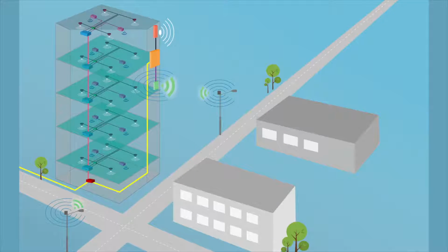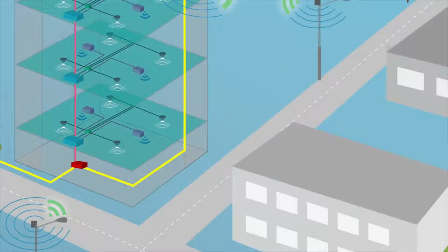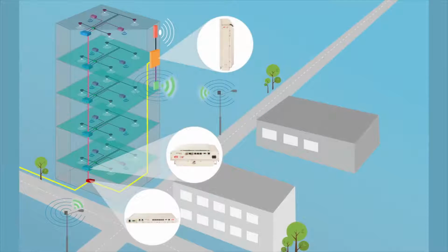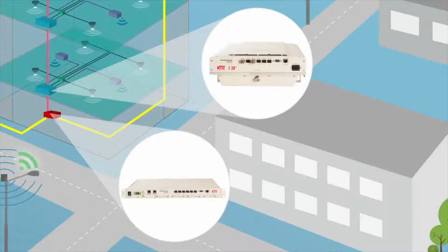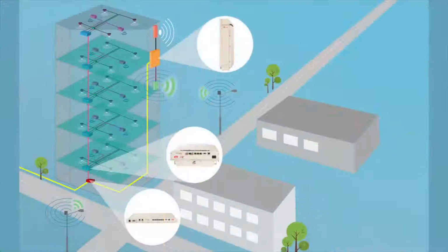The main purpose of the system is to provide indoor and outdoor coverage in areas that have insufficient RF signal quality. This is due to the fact that the RF signal from the macro cell, when passing through artificial and natural obstacles, incurs a loss, and as a result the RF signal quality suffers. The Dali digital distribution system is designed to provide optimum RF signal quality, and in that way enables higher quality of service and enhances user experience.